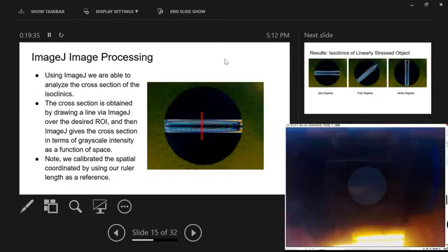And you'll see that there are dark fringes through the center here, which suggested to us that through the center of our ruler, we have a stress that is collinear with our analyzer or our polarizer, right? Because if our stress is in either the vertical or horizontal direction, which correspond to the analyzer and polarizer directions, the input light will essentially have no induced birefringence because it's in line with our stress direction.